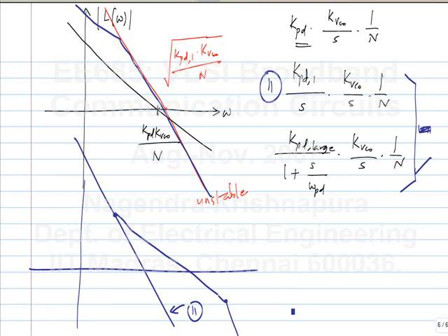You can think of either stabilizing the second one or increasing the gain of the first one. So this is the first one, okay, at DC and frequencies below the unity gain frequency, but you don't meddle around with it at the unity gain frequency. Okay. So this is how you have to modify it.